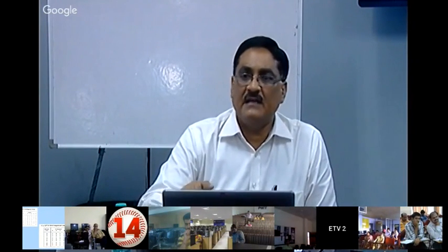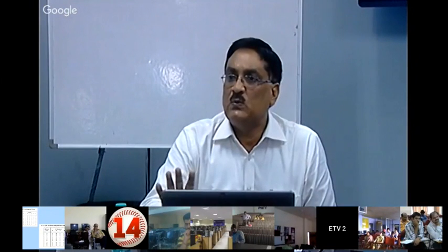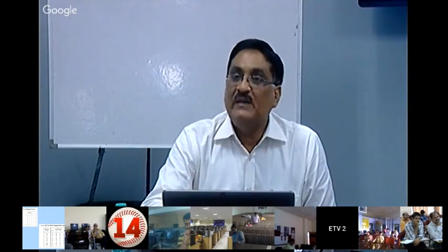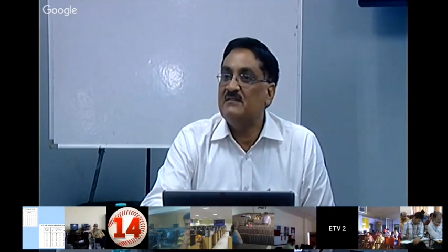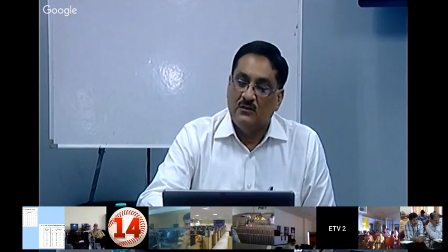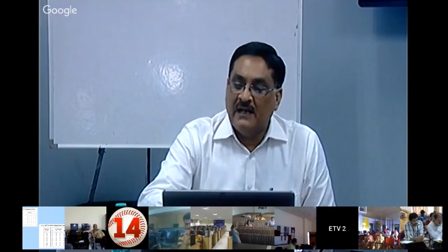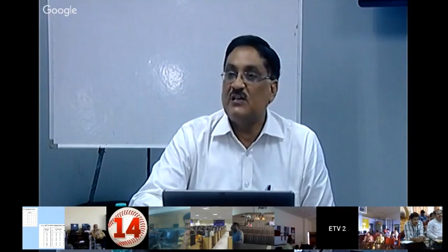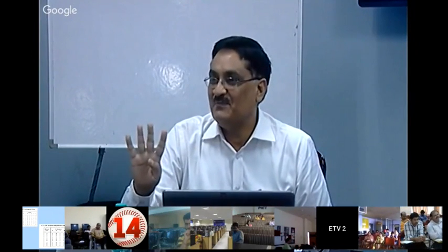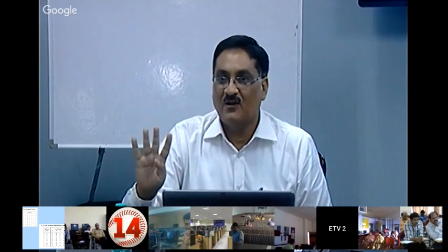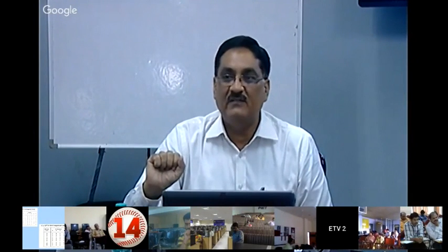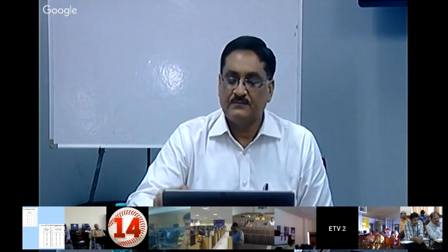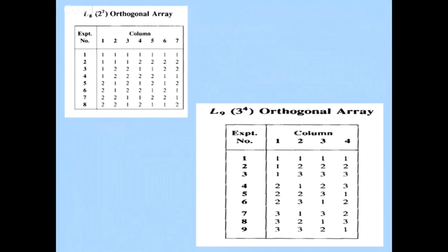I assign the current to column number 2. 1 means 10 ampere. 2 means 15 ampere, 3 means 20 ampere. So I think you can guess now that this L9 orthogonal array I can use to study 4 factors maximum. Got it? Is it clear to everyone? Is it clear? Okay. So columns I have explained.